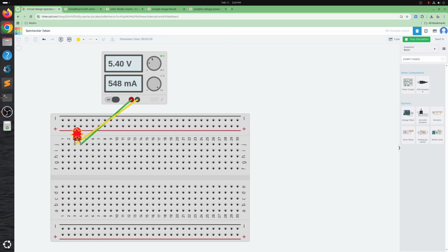voltage drastically. Okay, now if you see, it's not blinking. We are at 0 volts. Now I've increased it slightly. It's at 400 millivolts. So now it's at 1.20 volt. It's not blinking. Okay, now it blinks. Let's try to control the voltage a bit. So if you see, at 1.9 it's blinking, at 1.8 it's not blinking. So the threshold might be at 1.9 for this one.